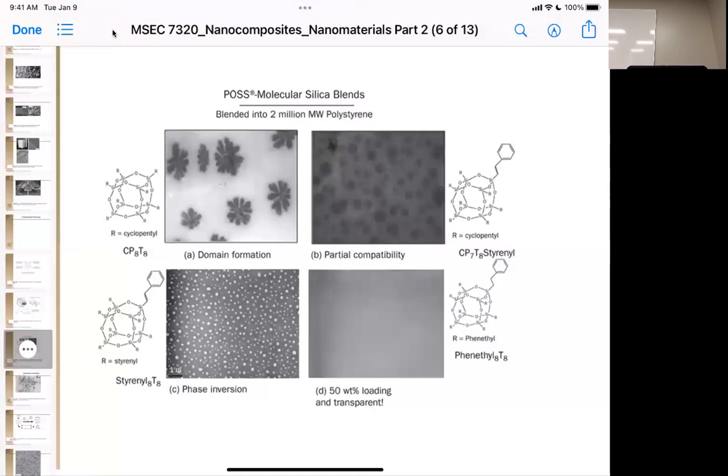What if we take it and change that compatibilizing group to be exactly like polystyrene is once it's polymerized? It takes away the double bond. So basically you have ethylbenzene. And if we go to that scheme here, we take out the double bond, add the flexibility that we see on the polymer chain, we can get 58% with no formation of crystallites from that system. So this is probably a first example of how compatibilization of the surface on our polymer, on our particle or our nanomaterial has a huge effect on its ability to be used for its intended purpose.